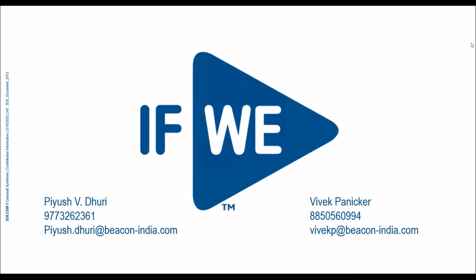So the first question is, is the node connectivity in mesh compatible for two different bodies? By default, it is incompatible in nature, but we have the control where I can tell the software to make the mesh compatible between the two components by defining a mesh control or a mesh setting between them. Let's say there is a source body where we have created the mesh and there is another target body on which you want to create the mesh. I can tell the target body that I want to connect it with my source body, so it automatically gets connected with my source body.